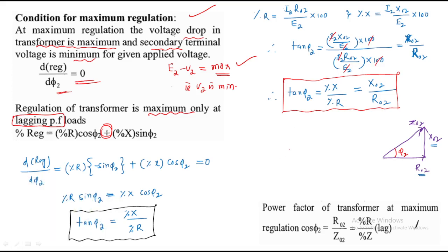What is the power factor of load? Cos phi 2 should be equal to what? R02 by Z02, which is equal to what? Percentage R by percentage Z. That is the power factor of